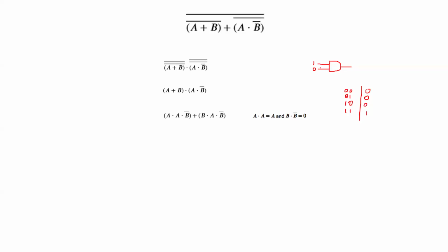The other way we can draw this is if you have an AND gate. Here's the output. Here's one input, and here's an inverter, like a triangle with the inversion bubble, and that is connected here, and these are connected together, and this would be B here.